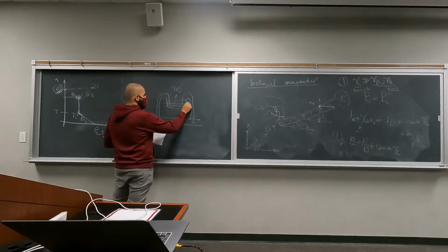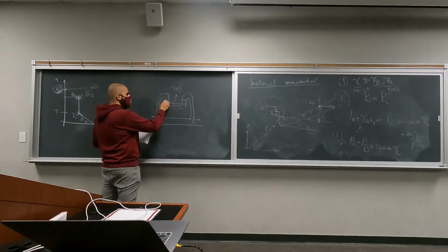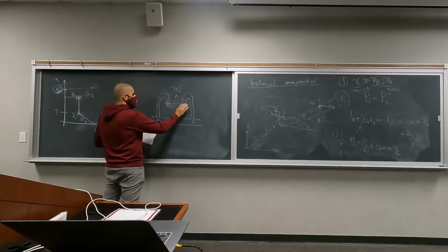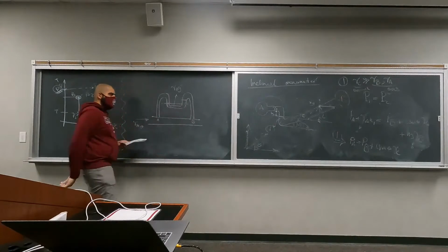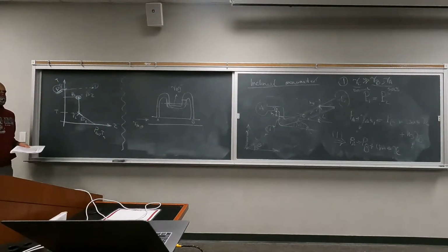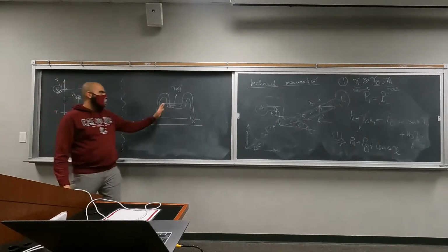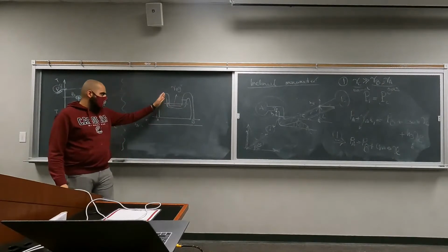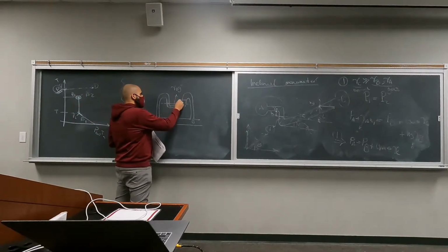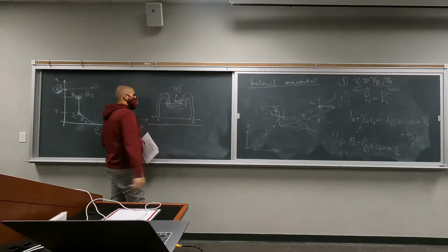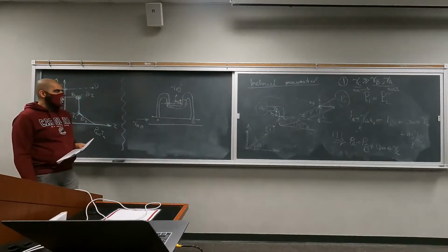The first thing you want to find is to set this height as your reference height, where the pressure between the two columns is essentially the same. And then you want to measure the distance from that location to all of the surfaces.